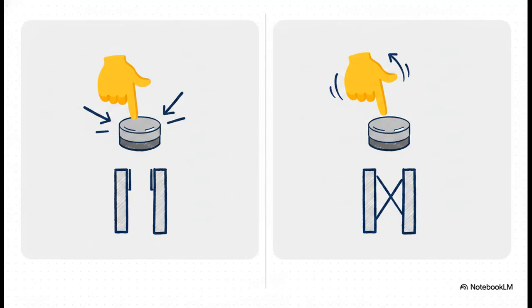Section 2, latching and memory bits. This is where we tackle the core concept of how the PLC actually remembers that a fleeting physical action has happened. A button interaction isn't just one magic event. It's a press and it's a release. The PLC has to distinctly register both of these states to count it as one complete interaction.